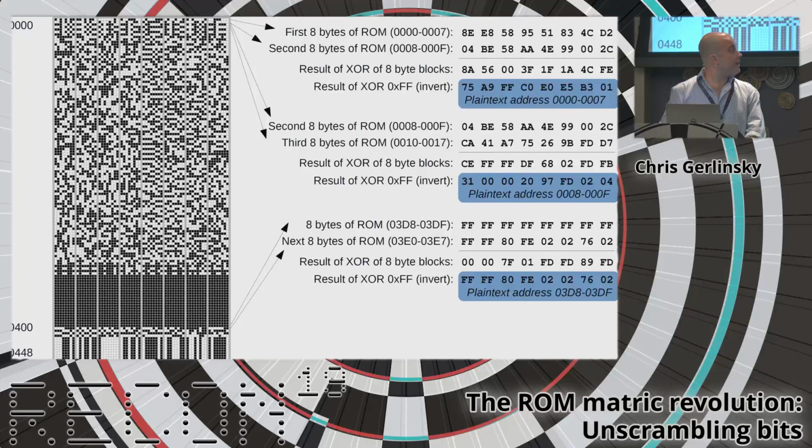The other main pattern that showed up here was that there's the empty space that's all FFs near the end of the chip. And that doesn't show the exclusive OR pattern in it at all. If I look at the end of that block, remember there was the 8 bytes that were not encrypted. If I take those bytes and I exclusive OR with the neighboring bytes, then I do get the sequential bytes after that decrypted. So they're doing something a little bit funny with the exclusive OR here in the empty space, but you can XOR the other bytes together and you get your plain text.